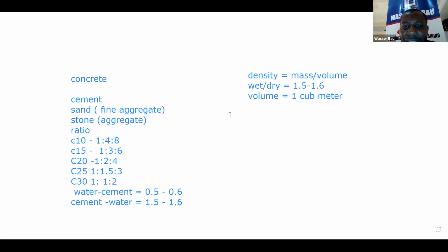Dry sand, 1,600. I agree with you. Density of sand, 1,450 over 2,000. Good. Njadiko said dry sand 1,600. I'll take Njadiko's own. Why? Because in engineering, you go for the worst case scenario. The less the density we get, the more the material, which is good on the part of the engineer.